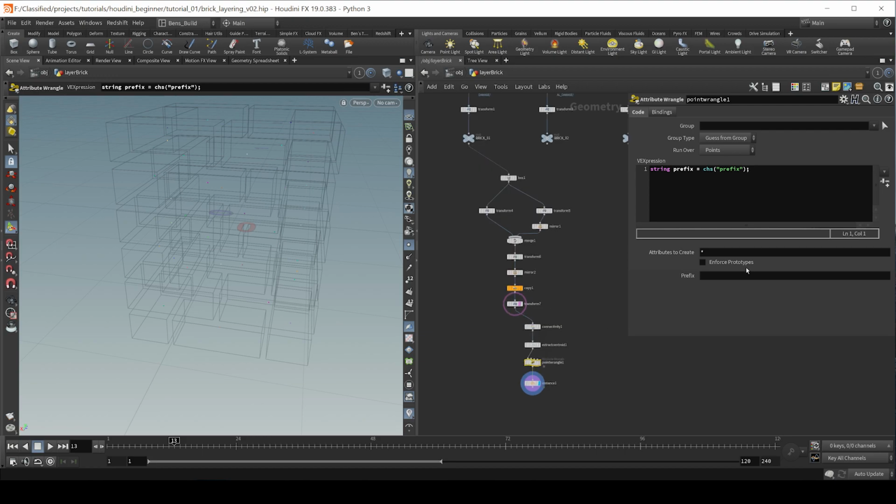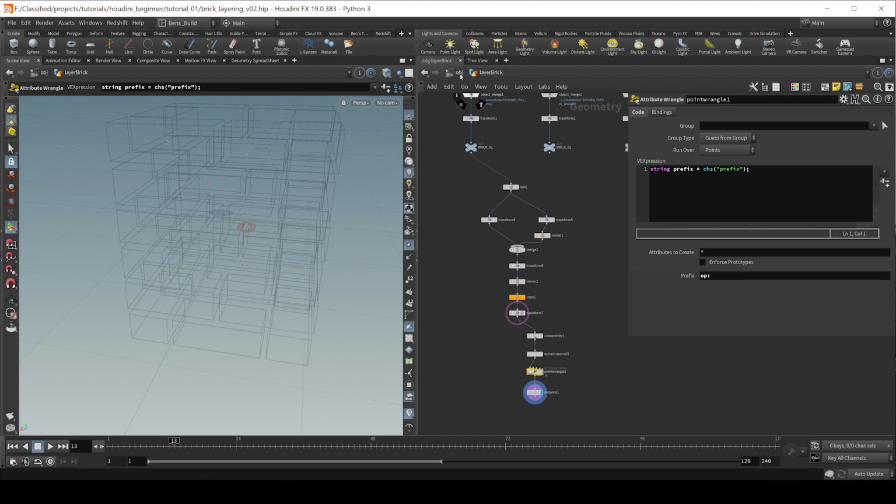And what I can do is, a lot of times when you instance things, you can instance it through a file path, like a location on your computer. But in Houdini, you can also reference things inside the Houdini file this way by typing an operator, so op, colon, and then the start of the path where it's located in Houdini.